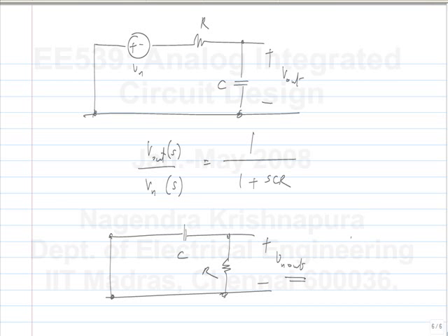So the noise of this is also kT by C. Again, this is somewhat like loop gain. It's not dependent on where you apply the input and where you take the output. If the circuit with the inputs disabled is identical, the noise will be identical as long as you are measuring at the same point. It of course does depend on where you take the output, but it doesn't depend on what you consider as input. Okay.